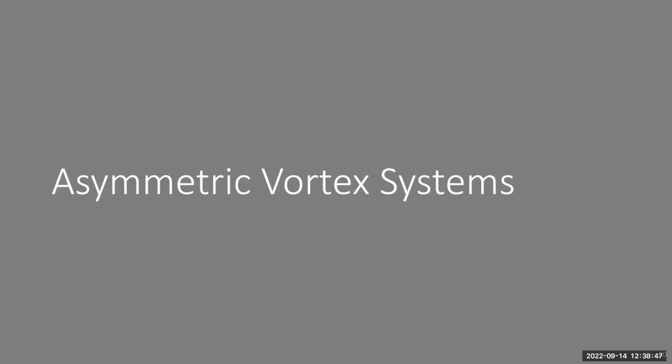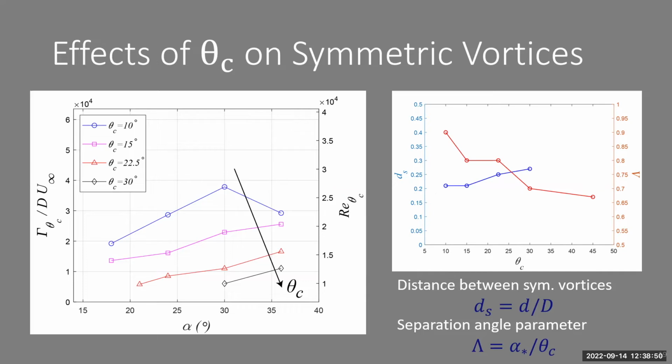So the distance between measured vortices, wouldn't that depend on where you chose to take the plane? Yeah. Because if you took it further apart, the relation might actually be stronger. Wouldn't it be better to take the angle rather than the distance? That's a good idea. What I did try to do to accommodate for that is I took a fixed location, y over d equal to 1 for all cases. And that's non-dimensionalized based on the diameter of each cone. But looking at the angle might be another way of seeing it. Qualitatively, you can actually see the separations.